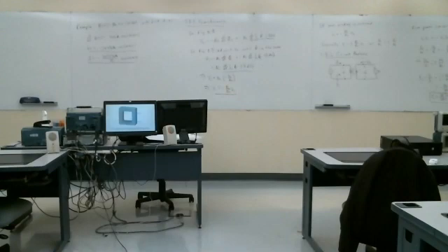The step up and step down refer to the voltage ratios and also the turns ratios. If the number of turns in the secondary is greater than the number of turns in the primary, it's a step up. If the number of turns in the secondary is smaller than the number of turns in the primary, then it's a step down. The secondary voltage would be smaller than the primary voltage. The secondary current, though, would be larger than the primary current.